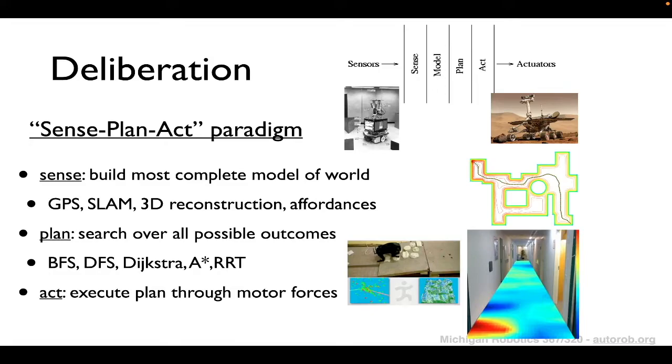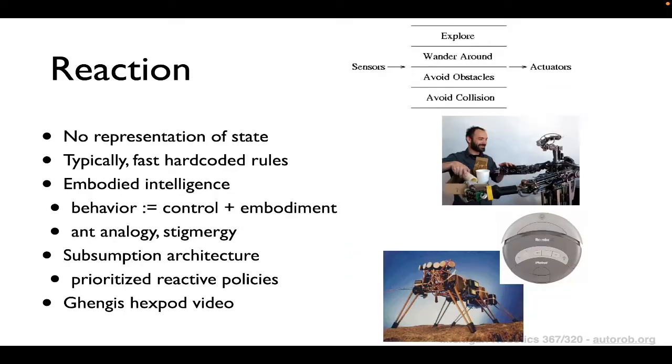So the algorithms that we talked about earlier in the semester, the graph search algorithms, certainly fell within the deliberative planning paradigm. Sometimes you'll hear deliberative planning paradigms referred to as the sense-plan-act paradigm, where you'll have some sensor input that has a feed-forward process to some planning algorithm, for example, the graph search algorithms that we looked at in this course. And then finally, as output from those planning algorithms, you would have some action taken in the world.